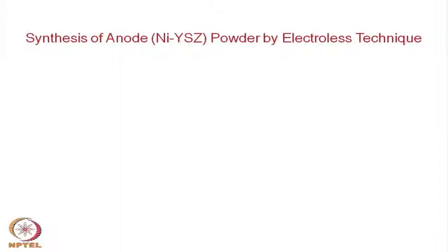There are other, of course much better, techniques where much finer powders can be prepared either by co-precipitation or by sol gel technique or maybe combustion technique. Okay. So, it is a high temperature combustion, either a solution combustion or gel combustion. So, many of these techniques can be used to make fine powders of these mixed oxides.